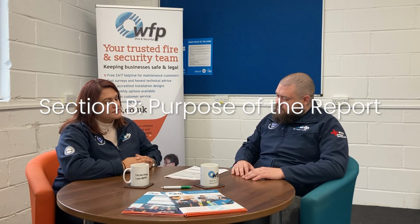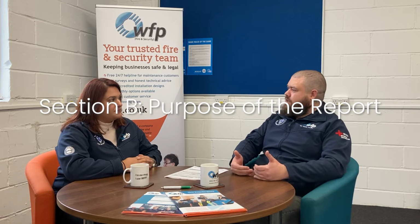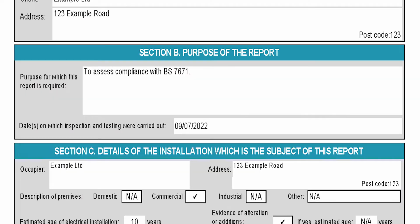Then we go to section B, which is the purpose of the report. So why are we doing this report? On this particular one, this is a 5-year check, so we say to assess compliance with BS 7671. But it could be a whole house visit, or you've just had a massive water leak and you want to check your circuits are okay. That's important: why exactly are we producing this report? So make sure that is what you asked for.